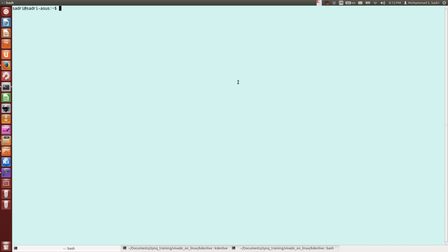Okay, now I want to test if xmd can recognize the programming cable. And I have not done anything. I have just installed Vivado 2014.3, and then I have sourced the settings64.sh file, and also during installation I told the tool to install cable drivers. So myself, I didn't do anything explicit regarding the cable drivers.